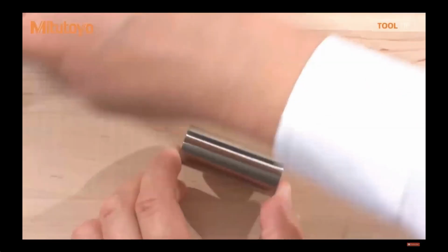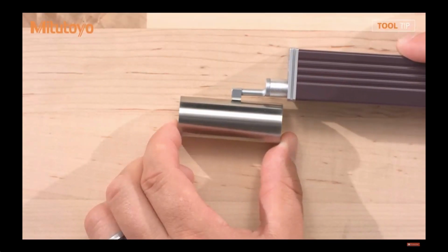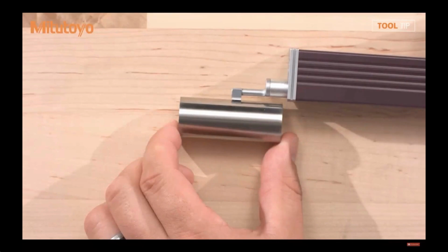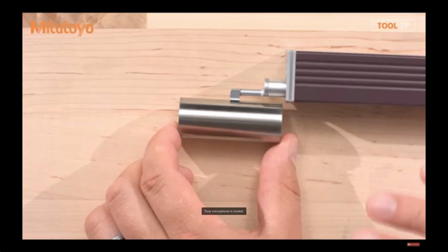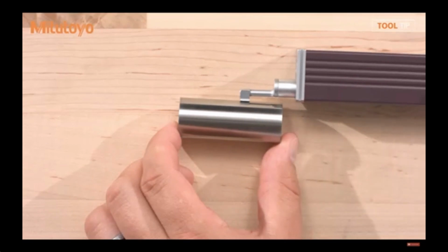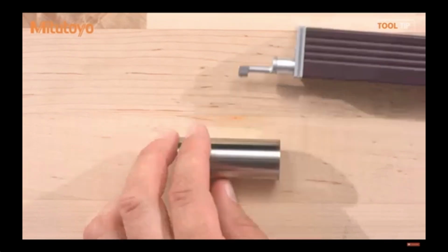Okay, so if you're measuring along the axis, a skidded unit would be great, because what's important with the skidded unit is that after it makes contact with the part, the skid is always in complete contact with the surface that's being measured. So if you look at the skid here, there are no gaps between the skid and the part anywhere. It's not sitting at a weird angle to where the beginning or the end of the skid is off. It's nice, even contact, to where if I were to move the stylus or the skid back and forth, it's always in contact with the part. And that's important because the skid is the datum, and if the datum isn't making good contact with the part, you get inaccurate measurements. Right? That is. So if you were to measure along the axis of this part, you'd be fine.